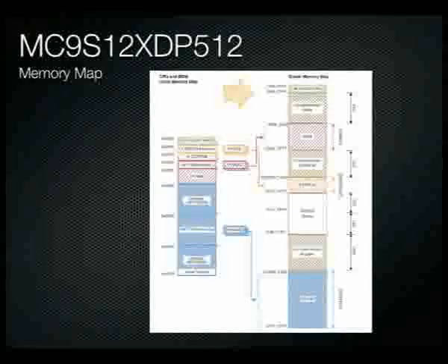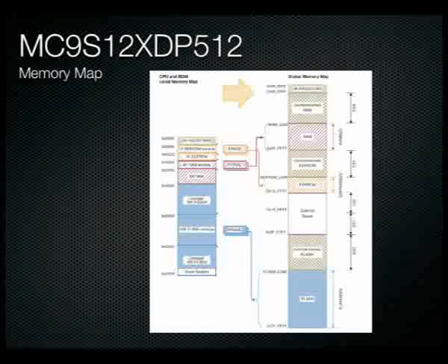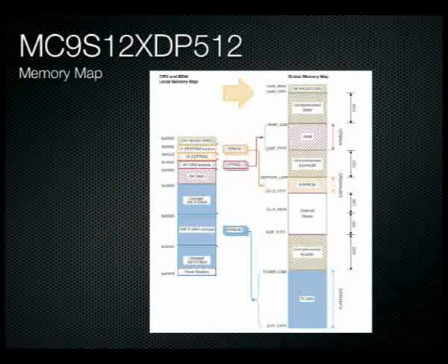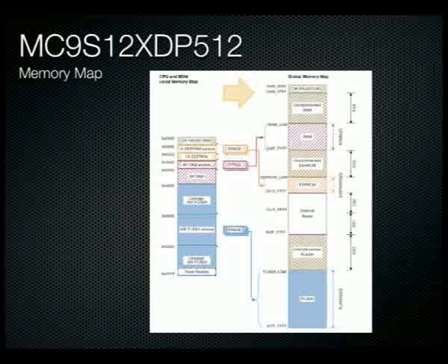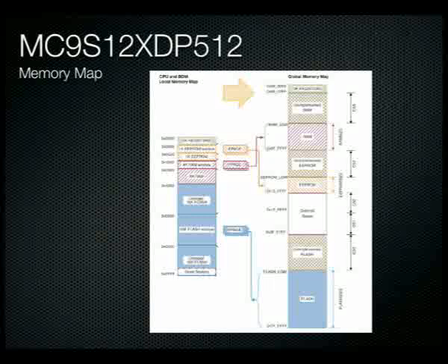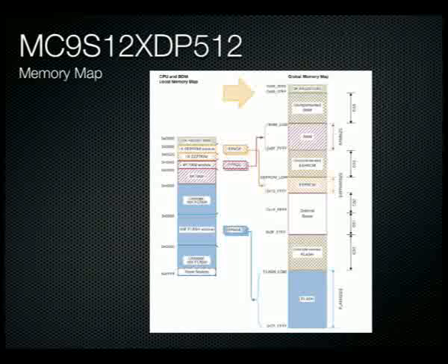So to give you another example of a memory map, this is the memory map that we use inside our processor. And you can see that inside this memory map we have various memory mapped technologies. We have our I/O register set living in the bottom 2K of memory. So in the bottom 2K of memory we have our GPIO registers, our analog to digital converters, our timers, our pulse width modulators, our serial subsystems, and all our other various control registers for the microprocessor itself. All live in the lower 2K of memory on our memory map, so they are all memory mapped I/O devices.